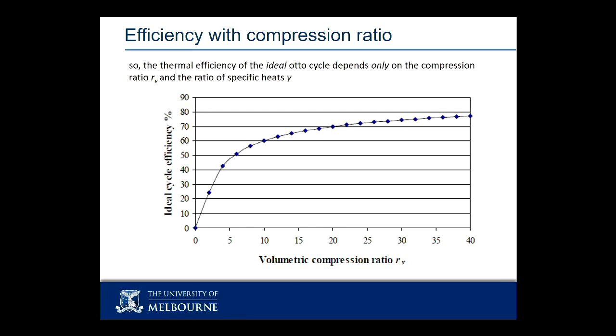The thing that stops you from having a bigger and bigger compression ratio is as you squeeze up, you get hotter, and gasoline likes to burn, and particularly it likes to auto-ignite. And that auto-ignition is referred to as knock because it goes bang before you are ready for it. If your flame burns before you're ready for it, it means it catches fire while I'm still trying to push up against it. And so now my car engine shudders to a halt because it's trying to fight up against this massive pressure release. So I don't want that to happen.